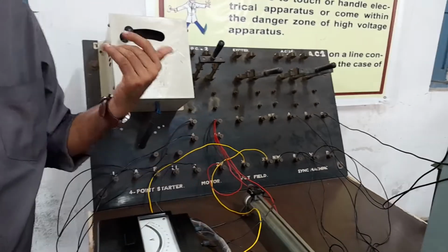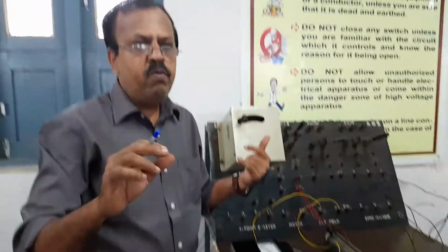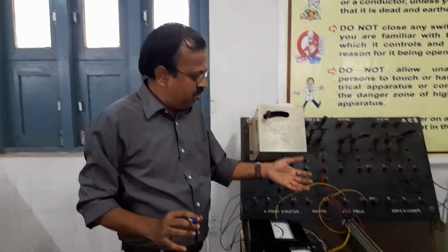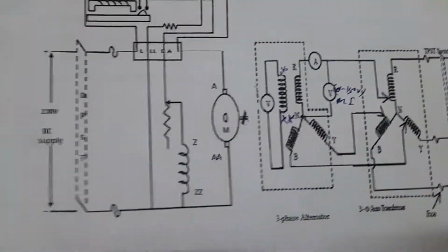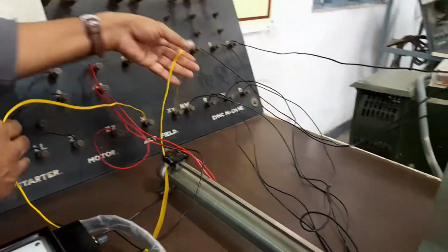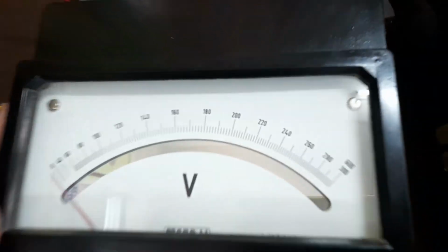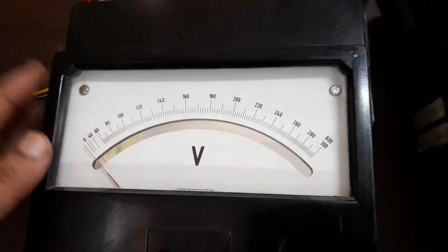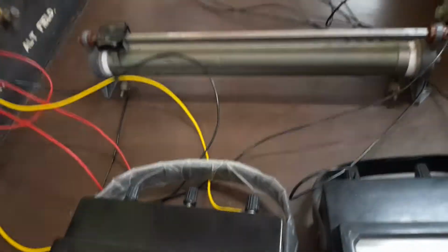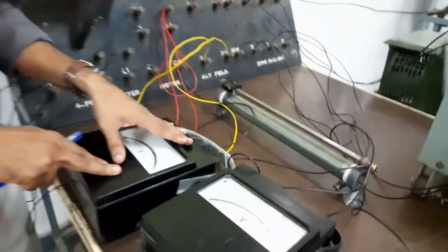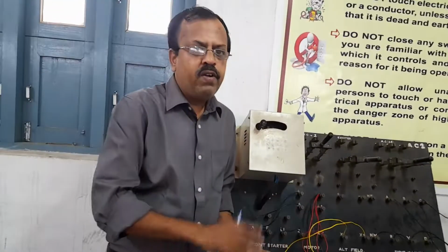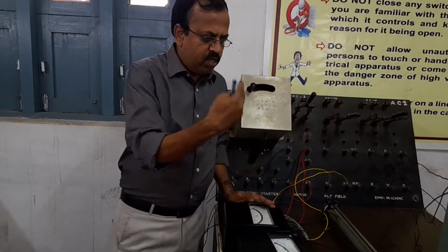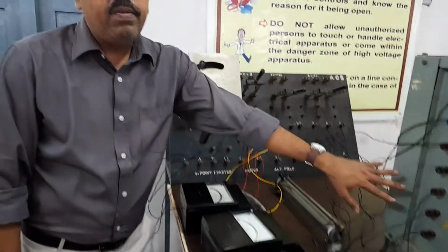Next, as I said, the voltage across the field winding is to be kept open. So we simply connect a voltmeter as shown in the diagram. You can observe this is X and this one is XX. We take this as the alternator field winding, and across this field winding a voltmeter is connected. The purpose of this voltmeter is to indicate whether the phase sequence is matched or not. If you get any reading in this voltmeter, it means the phase sequence is different, so we need to change any two terminals of the alternator.